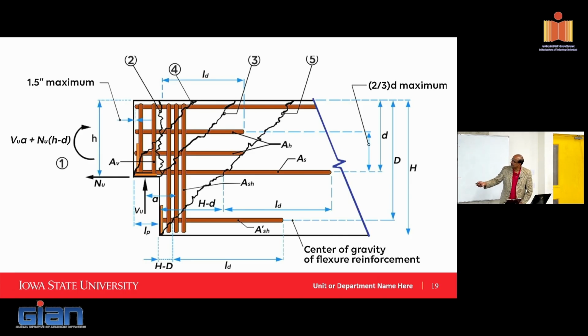So this is a standard detail, and there are different ones. In this particular case, they use what they call T-headed bars as well as stirrups and vertical longitudinal reinforcement. They would use, for example, bars going here with 90-degree hooks, so that this crack, what's shown here, has to be crossed with a sufficient amount of steel. So someone has to check and make sure that such a failure will not take place.